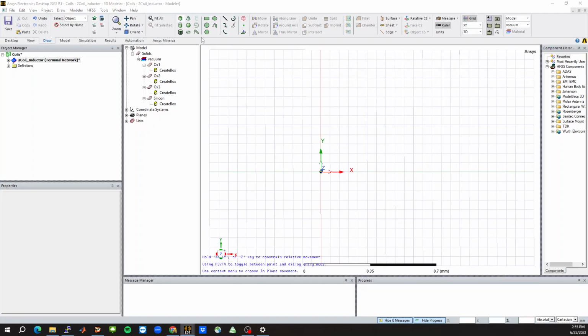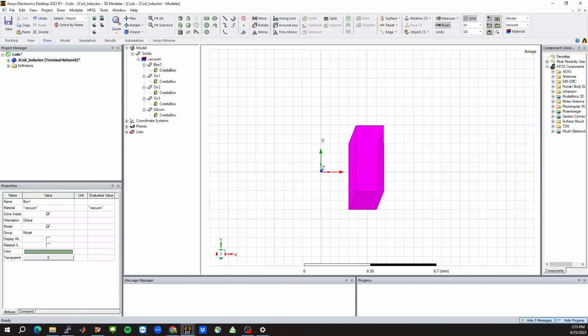So let's start by making one section of the hexagon. So I'm going to make a hexagonal inductor because that would pass DRC rules. So I'll just make a box, and then from this box I'll start drawing out the values.